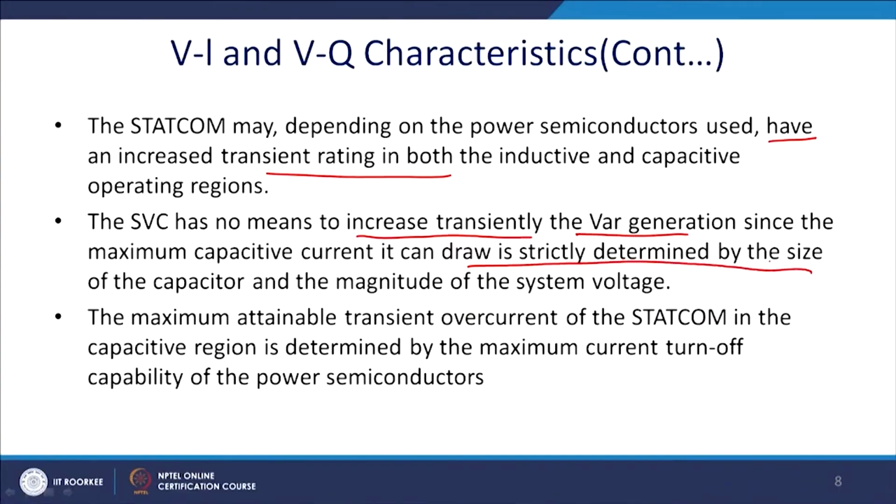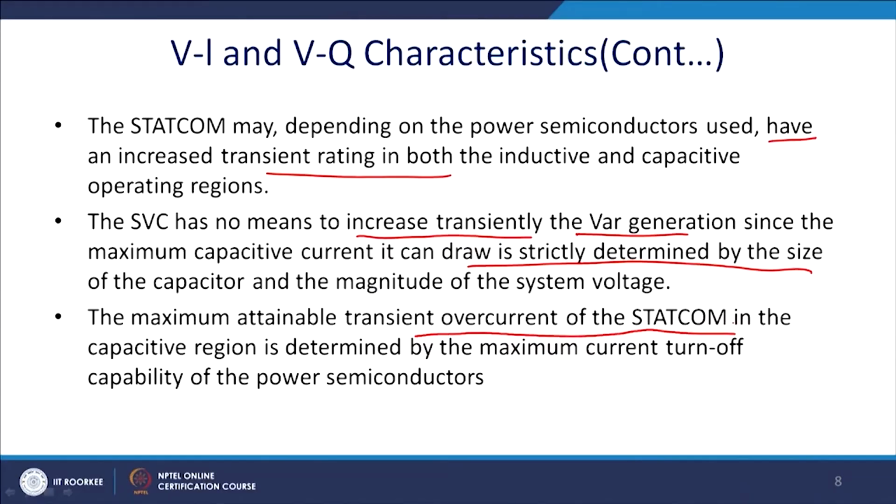SVC has no means of increasing transient var compensation, since the maximum capacitive current it can draw is directly determined by the size of the capacitor and the magnitude of the system voltage. So, the thyristor is almost a passive device here. The maximum attainable transient overcurrent of the STATCOM in the capacitive region is determined by the maximum current turn-off capability of the power semiconductor, but in most cases it will be determined by the capacitor rating